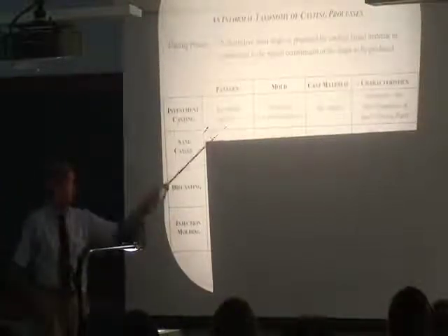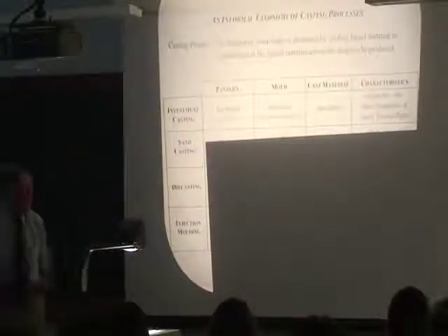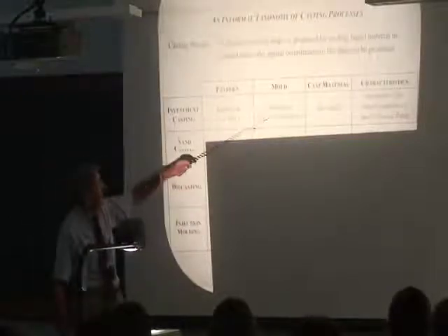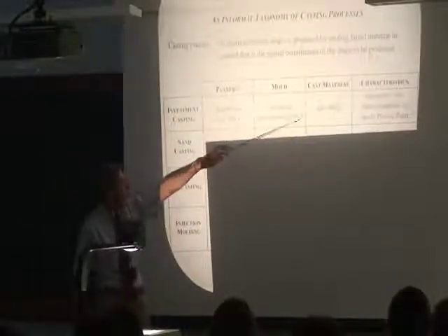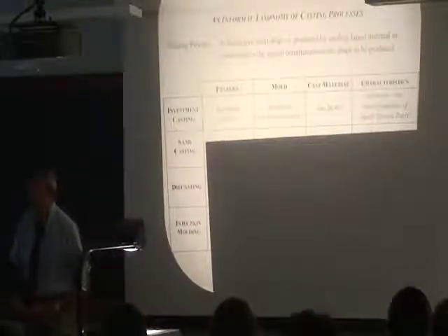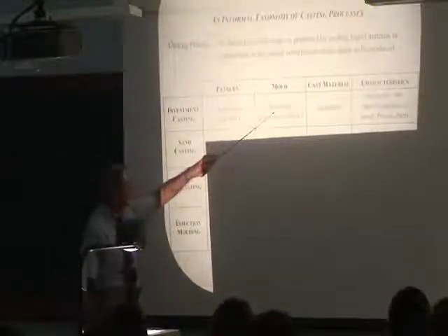You have to get the pattern out. How do you do that? Well, you just heat the mold. And wax melts and it runs out. But then, of course, you've lost your pattern. And then once you have your mold, you pour in your metal. Then you have to get your cast part out of the mold. How do you do that? You break the mold. And so the mold is sacrificial too.